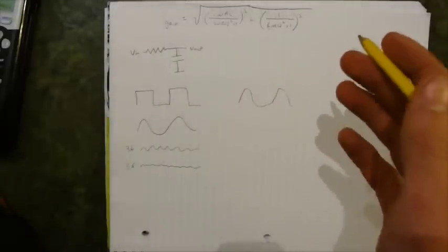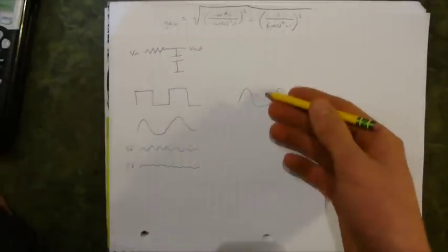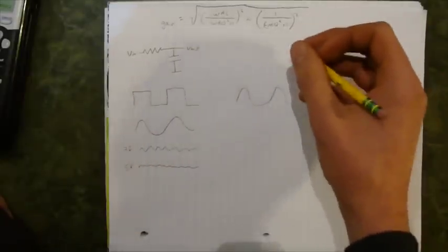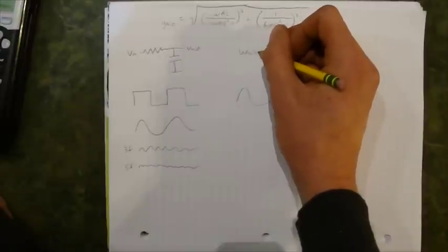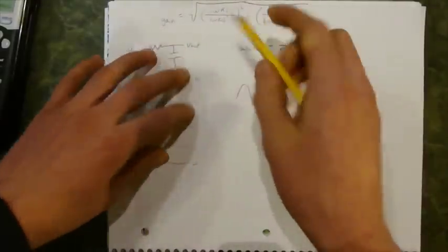So we want to solve for our resistances and capacitances of the circuit so that we maintain this signal and attenuate these signals. So the cutoff frequency for an RC filter, omega cutoff, is equal to 1 over RC. We want our cutoff frequency to be, let's say, 60 kilohertz, because our square wave will be anywhere from 44 to 48 kilohertz.